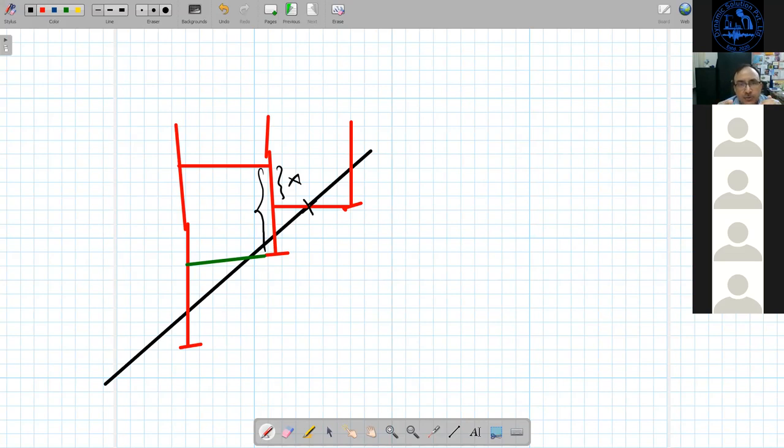We don't have to connect the plinth or the foundation in cases where it will give rise to short columns. Short columns are to be avoided. Means it is only to provide at the plinth level only. Sorry, it is only to provide the beam at the plinth level only.